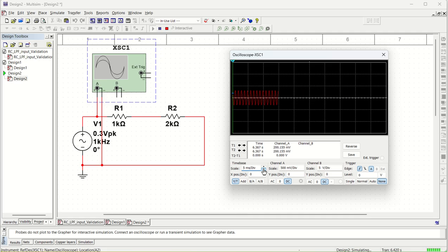And this one I am going to make it like this. And trigger voltage I need to set, otherwise it will be a little tough to view the waveform. Anyway, you understood how to set this and how to check your waveforms properly, right? So I am going to make it 200 millivolts. So 200 plus half of that, that is 300 millivolt output.